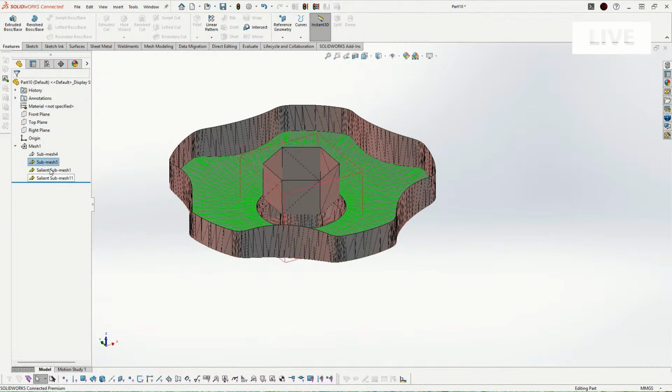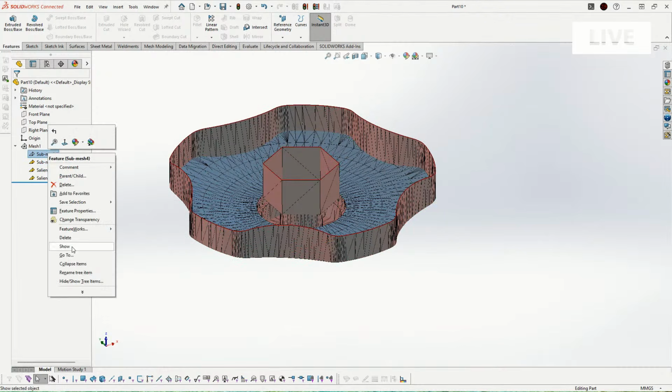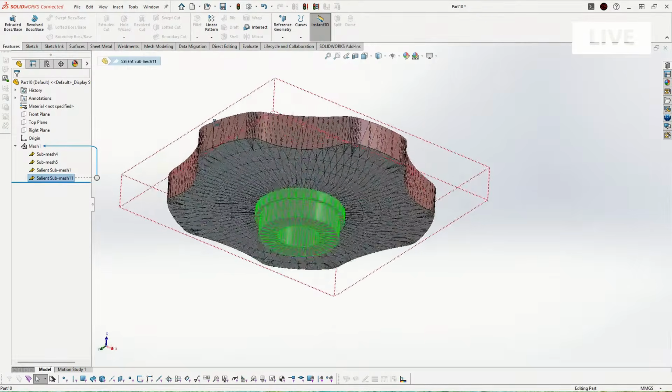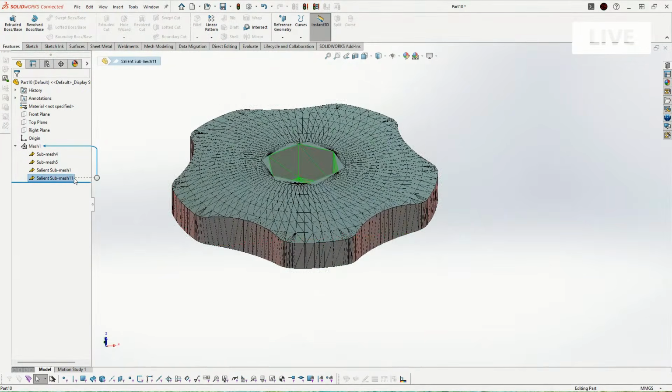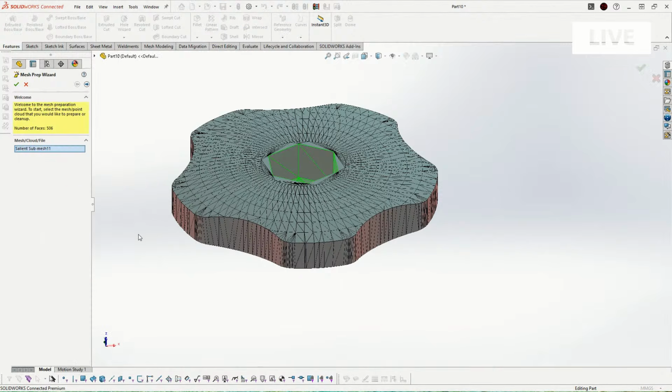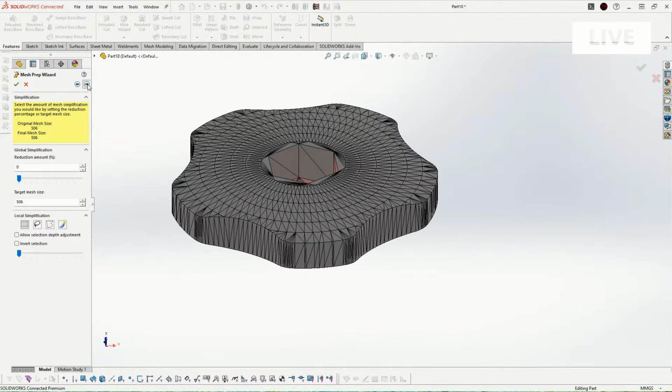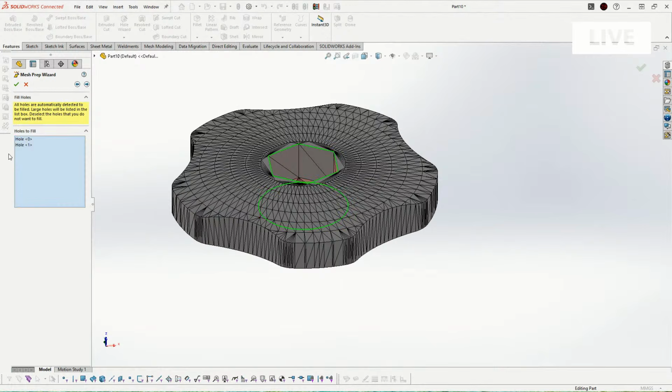So for a long time I was wondering how I make this submesh a separate mesh. And the answer was extremely easy. You select the mesh that you want to take out, right click and go through the mesh preparation wizard. Now, because we have some holes, it will ask to fill the holes, but I don't want to.